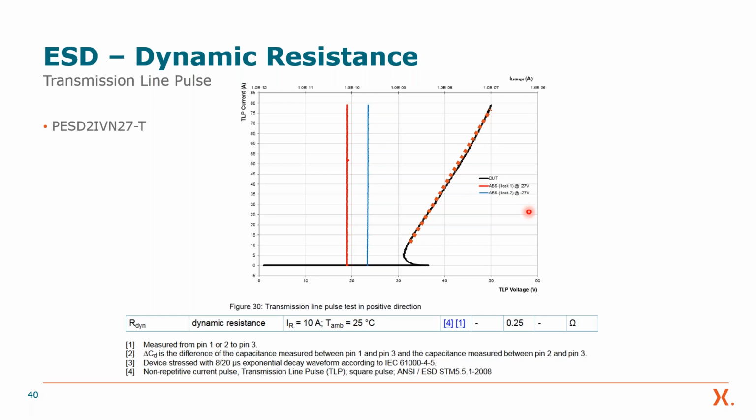Of course, you have some boundaries. For example, this diode is for CAN and LIN bus, and you have to be short to battery robust, so you cannot go as left as you want, but you should be as left as possible to have a good protection scheme. More details on this we will discuss next week with respect to the different interfaces we see in a car.